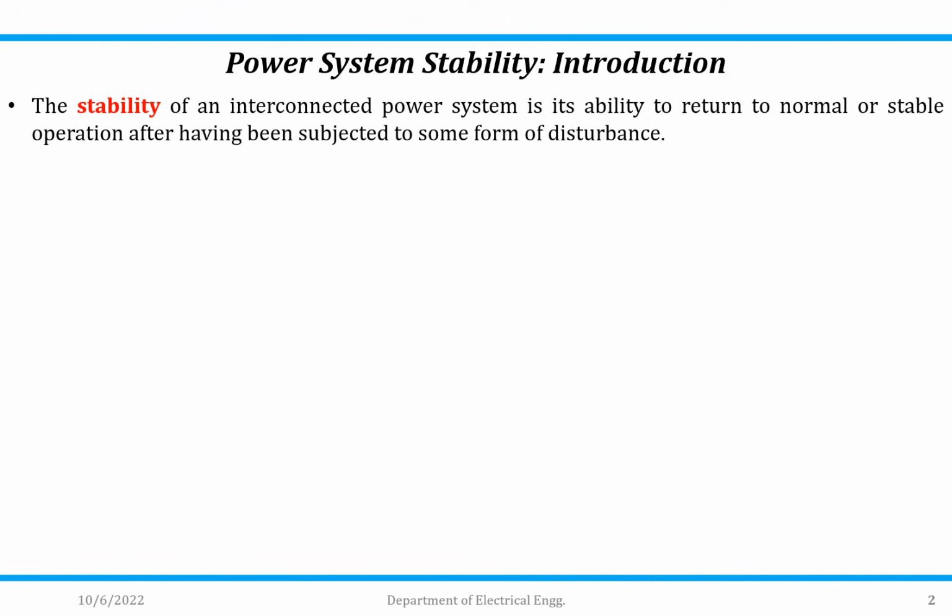The power system is an extremely non-linear and dynamic system with operating conditions or parameters which are continuously varying. Hence, stability of the system is a function of the initial operating condition and the nature of the disturbance. The disturbances could be major ones such as a fault, sudden loss of a generator, short circuit of a line or a combination of such events. Load changes continuously, which also affects the input side.